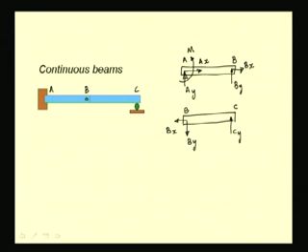Now, let us see how many unknowns we have. We have 3 unknowns at A and 2 unknowns at B, totaling to 5. And from this free body diagram, this Bx and By have already been accounted for in this free body diagram. They are only opposite in sign, so they do not constitute a new unknown, and we have one more unknown, that is Cy. So, we have a total of 6 unknowns to be determined.